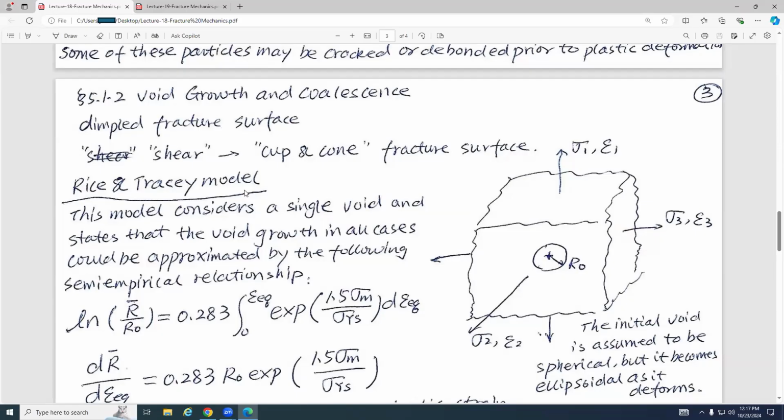Bobby? Brittle is going to be like a clean cut, but ductile is going to neck a little more, like when it stretches. Yeah, okay, great, thank you. So when a brittle material breaks under tensile loading conditions, it will have two very flat surfaces. Why? Because there is no plastic deformation, right?